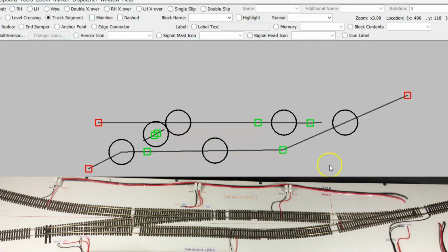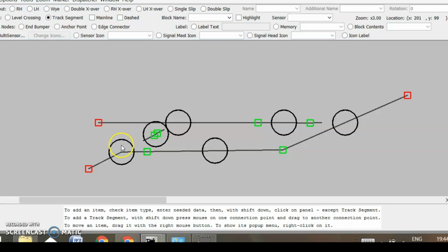Now at this point we can do some really cool things, and that is interlocking, without doing anything sophisticated. Now, as we have discussed, if you remember, these two turnouts, 101 and 102, actually form a crossover. It's always a good idea, whenever you're designing a crossover, that both the turnouts are interlocked. So, depending on the position of one turnout, the other turnout should be thrown accordingly. So let's see how we can do that here.